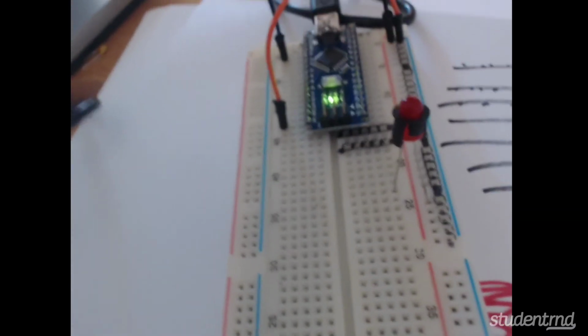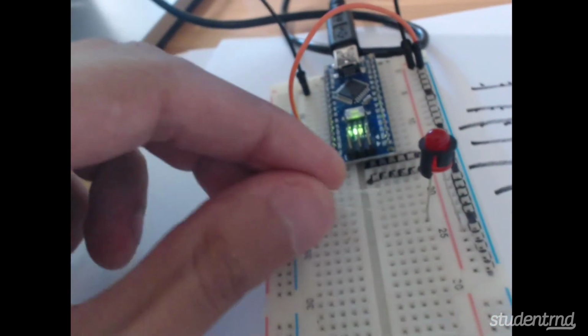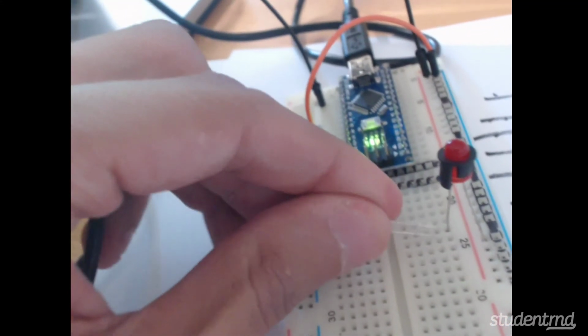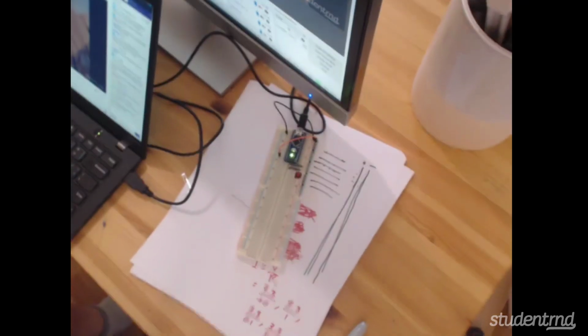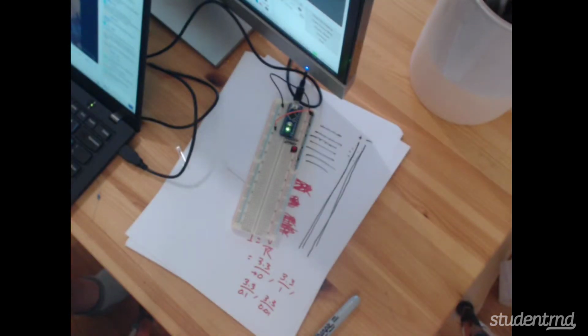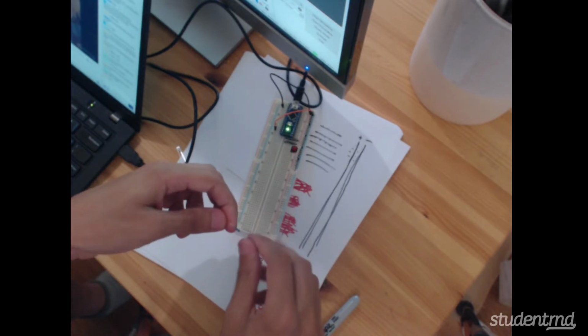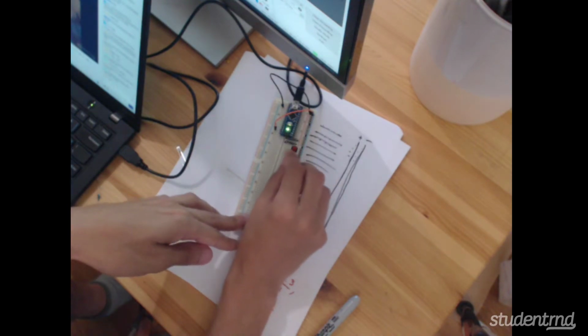Now what's happened is that every single thing in this same row, every single thing along here, is now connected to this pin. So what we want to do is connect that pin to a resistor. So I'm going to go ahead and get a resistor. Now what resistor do we want? Well, we could figure this out depending on how much current we want our LED to use. We can use Ohm's law. I'm going to tell you right now that I'm just going to use a resistor that is 82 ohms.